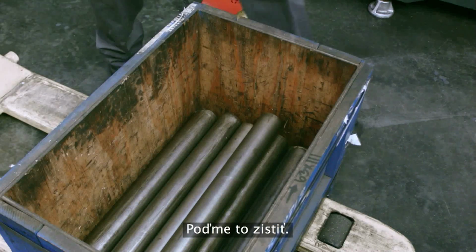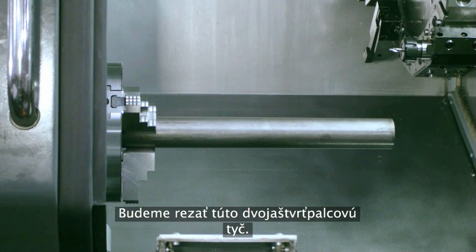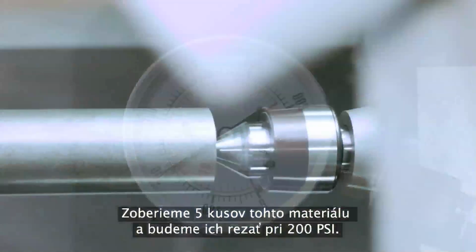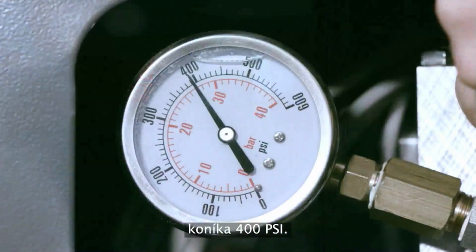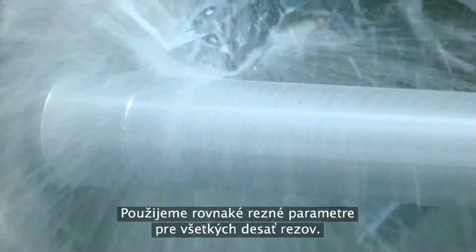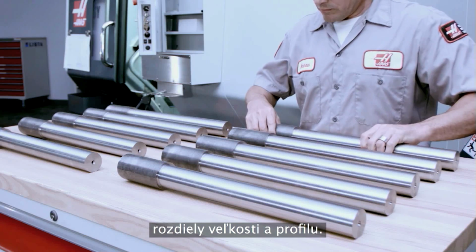Let's find out. We'll be cutting this 2 1/4 inch diameter bar stock. We're going to take 5 pieces of this material and cut them at 200 psi. Then we'll take 5 more pieces of that same material and cut them with a tailstock pressure of 400 psi. And we'll use the same cutting parameters for all 10 cuts. Then we'll line them up and measure them for differences in size and profile.